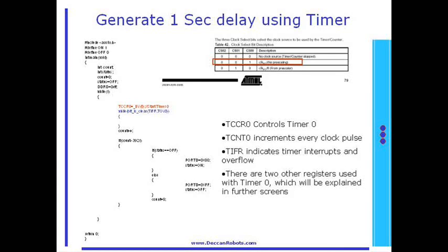As we know, timer 0 has an empty bucket type of register named TCNT0. This TCNT0 gets incremented every clock pulse. As the TCNT0 reaches its highest possible value, the timer overflow flag located in the TIFR register is set to high. This indicates that timer 0 has completed 1 cycle of its operation. Using a while loop, we have monitored the timer overflow flag TOV0. This while loop will end as the TOV0 flag is set to high.